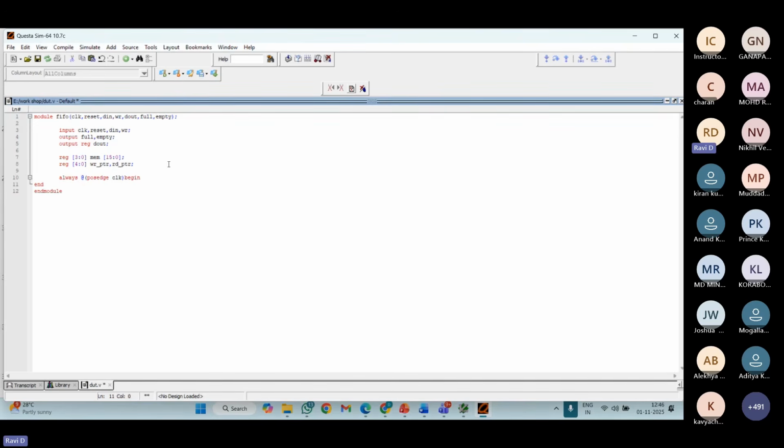First, what I need to do is reset. Usually my circuits are in an unknown state. That means my memory is also in X state. All the locations we have here are by default having X. It is going to store X. So here I need to bring my circuit from unknown state to known state.